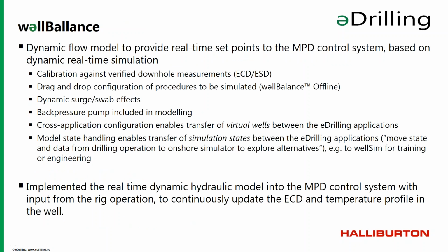Yes, and then a bit about the WellBalance, which is the hydraulic model that Halliburton is using in their system. This is a dynamic flow model that we use to provide real-time set points to the MPD control system based on dynamic real-time simulations. So the model gives a pressure set point for their MPD choke in real time during the operation, and that is calibrated against the verified downhole measurements.